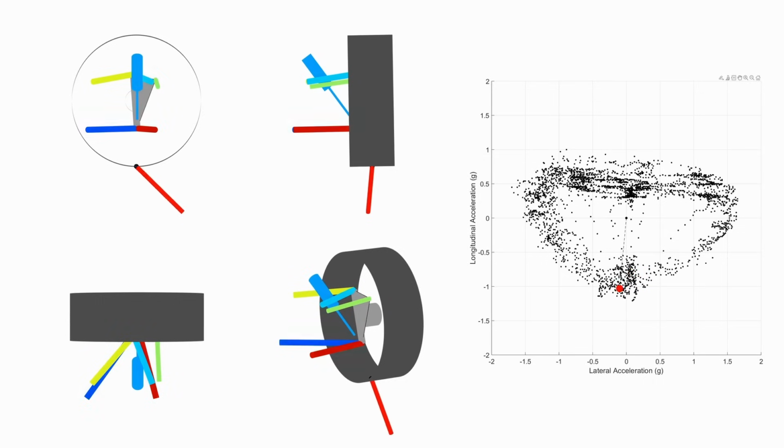And that's because for most cars, the suspension isn't actually moving that much. It's still roughly in the same place. And that means these loads are probably good enough for doing our basic sizing of components, where we're already going to apply a healthy safety factor. They would definitely be more limited if we were trying to apply these loads to a handling study of the vehicle, and that's where we may actually want to mix this sort of method of calculation with some of the moving geometry that I've done in a previous video.